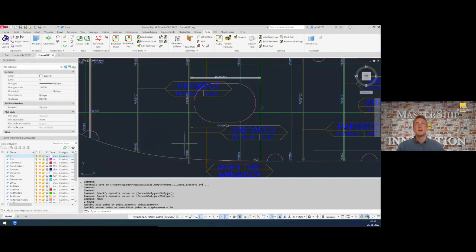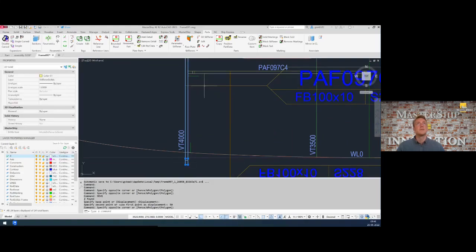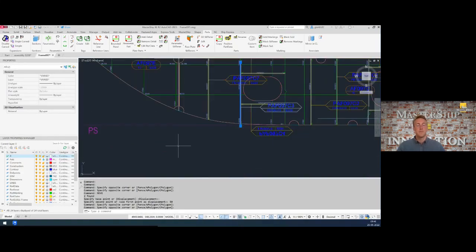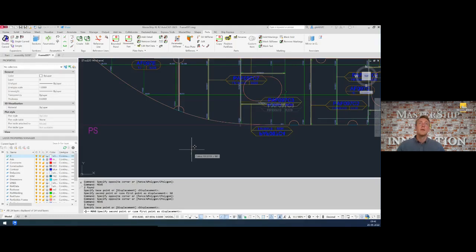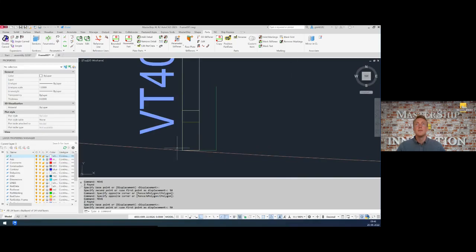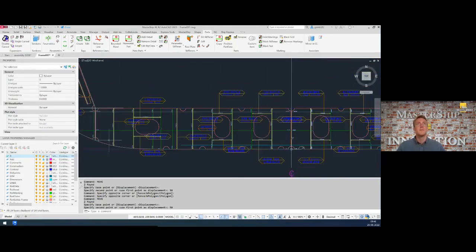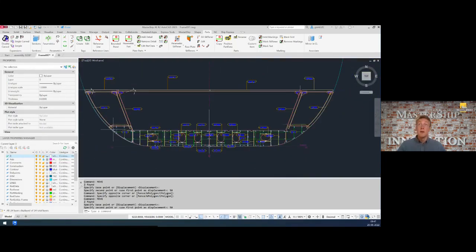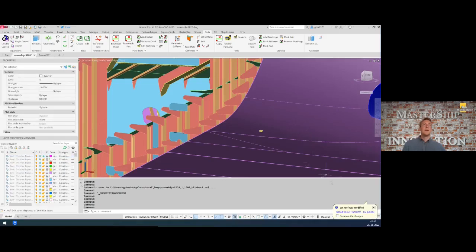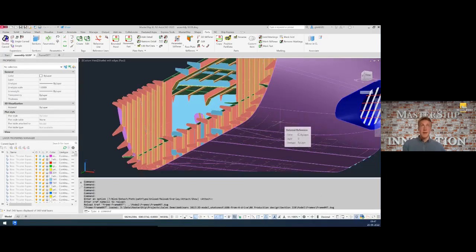And I think it was also clashing on this side. Let's adjust it, also by 50 millimeters up. So now we have no clash anymore. So I fixed the clash in my 3D MasterShip model. And here in the assembly, it will be updated. I reload this frame, yes. And you see it's now gone.